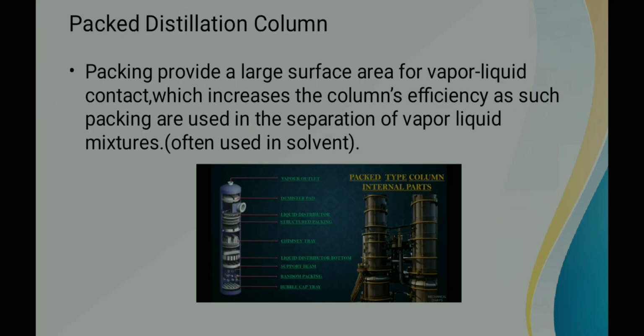Let us see the packed distillation column. Packing provides a large surface area for vapor-liquid contact, which increases the column's efficiency. Packed columns are used in the separation of vapor-liquid mixtures. This tells us that it covers a large surface area compared to the tray column.